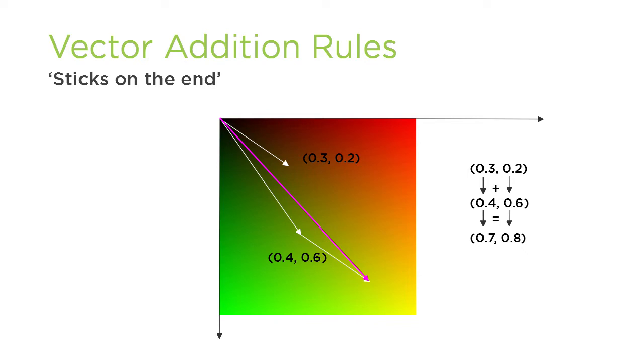Then when our texture is sampled, it will sample the pixels with an offset. One interesting thing is that when it comes to addition, it doesn't matter which way round you add them together, you will get the same result. Now we've seen this ability to provide this new UV input, and we have seen what the UV addition is actually doing, let's see this in action in Unreal.